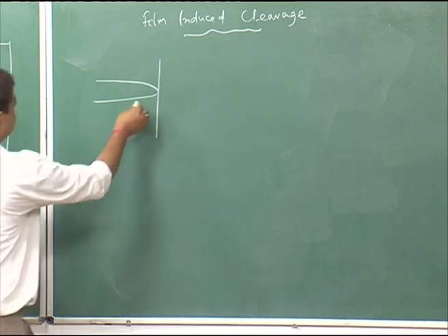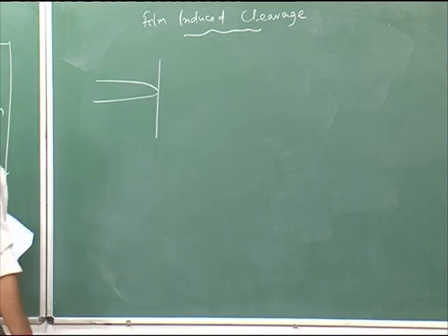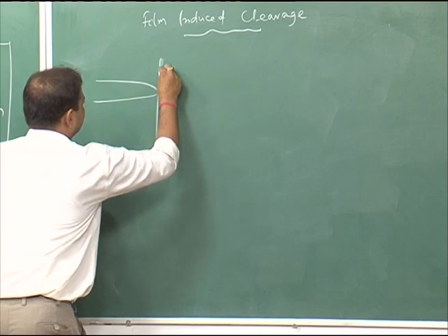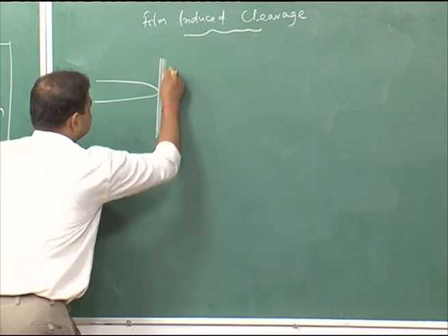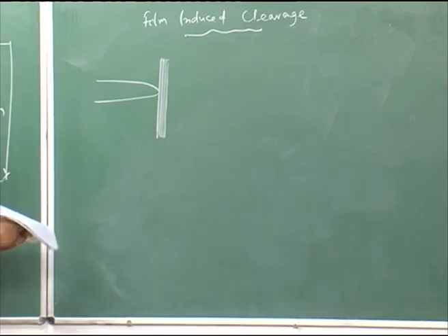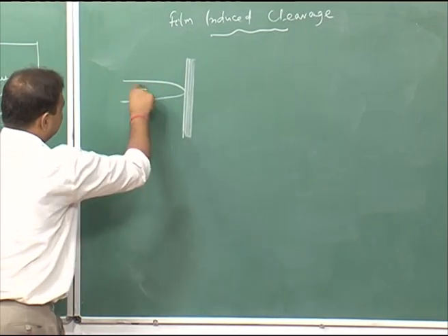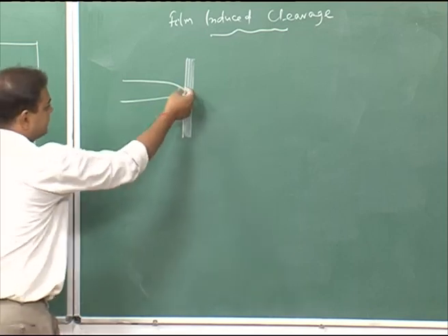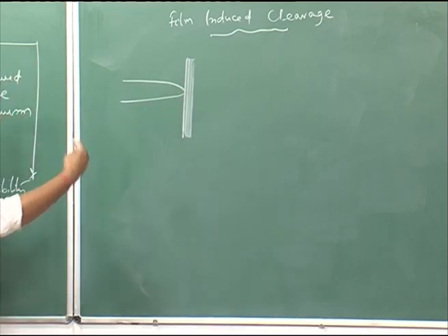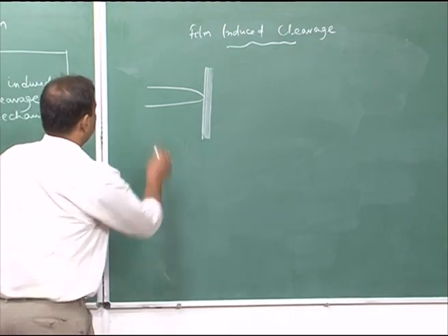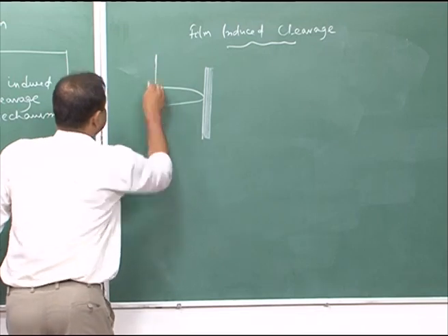Now, here we have a dissolution, and that corrosion reaction leads to formation of a passive film. It is almost similar to tarnish rupture, but the salient difference in this case is the film is forming at the crack tip, because at the crack tip zone the metal is exposed to the solution, and this corrosion reaction leads to the passive film formation, and this is under tension.